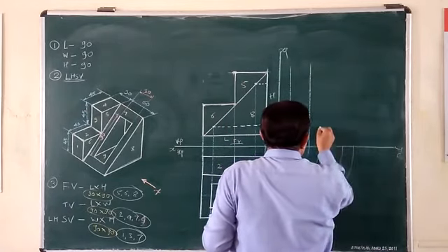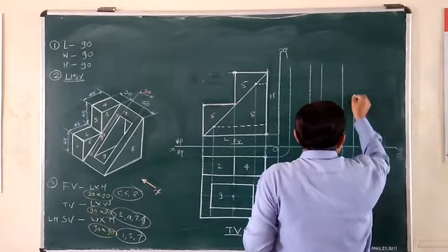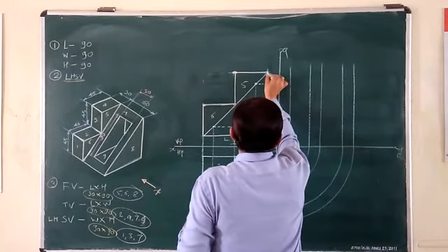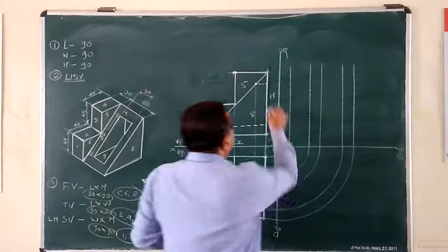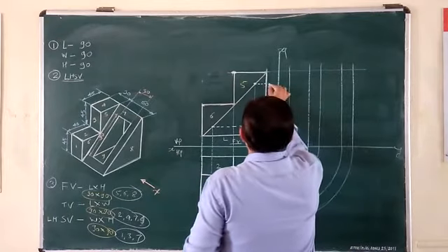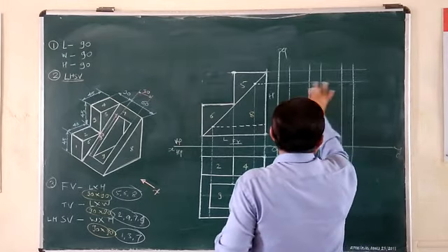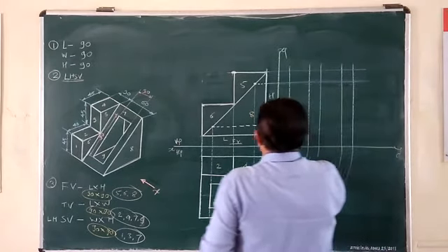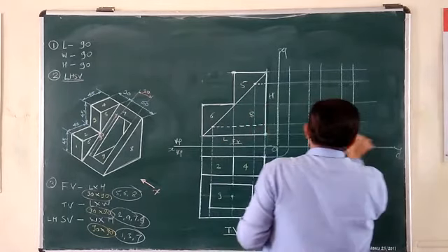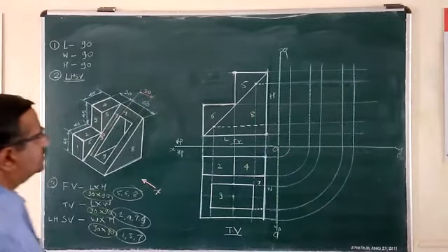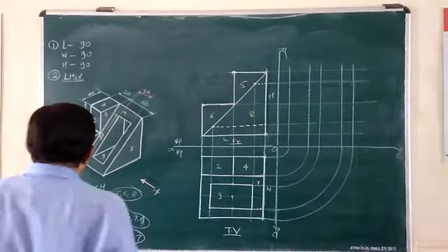We are going to construct its end view, its profile view, or specifically we are constructing its left hand side image. These are stretched from the top view. Similarly, the reverse: from the front view, cross projection lines you have to stretch back from the VP over the profile plane, PP. Projectors should be parallel to each other. Yes. Okay. So these cross projection lines will yield us the ultimate shape and size of the left hand side.